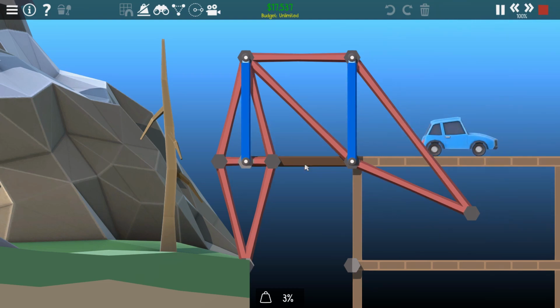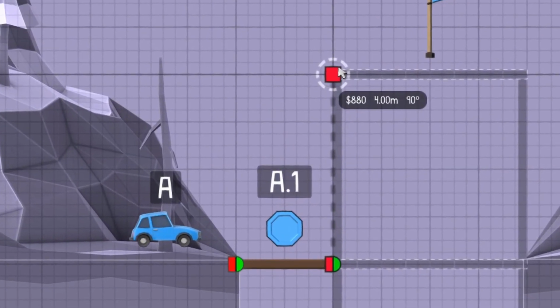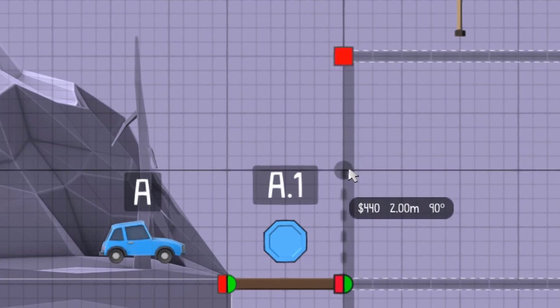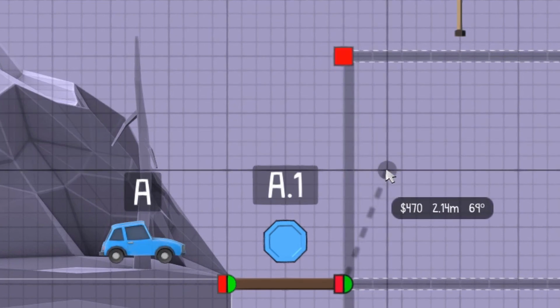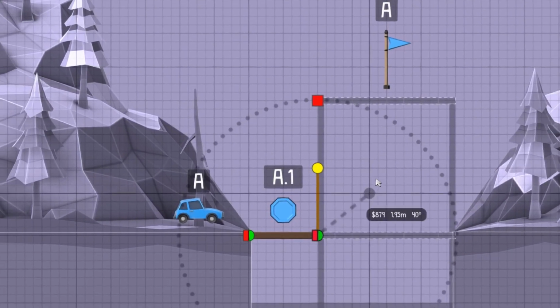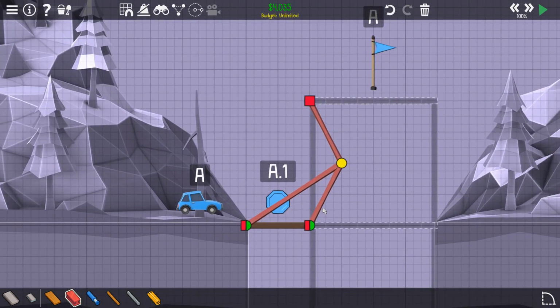Let's try this but scaled up. We now have to lift the road 4 meters. Half of 4 is 2. So we need to put the guiding arm 2 meters from the end. The guiding arm is going to be in orange to show that's the part that's moving.